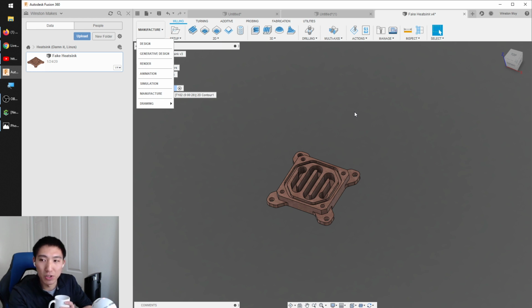For the most part, you can treat HDPE like wood, like you can plow through it pretty quick, but there are some cutters that are going to work better. I don't know how well our 301 and 302 are going to work in HDPE. Plastics really like having a sharp knife cutting edge on your end mills, and the 301, 302, and the Amana RC 1148, I think, they look and act more like card scrapers than anything else. The cutting edge is perpendicular to the rotation of the tool.